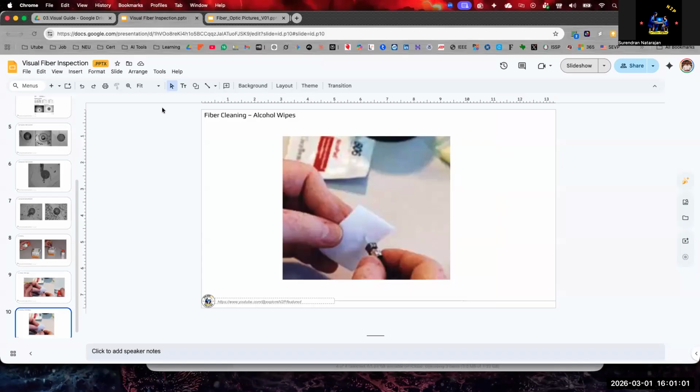The major part is safety in fiber optics. If you are going for a certification, safety is important. You saw that fiber is like a very thin hair. If it is broken, there are pieces, and you can't see those pieces on the floor. It is virtually impossible to see them. So it might be sticking in your hand. You wouldn't know, and by accident, if you swallow those things, that is a very worst case scenario. It may hit your eyes, nose, get inside your body. That is a very dangerous thing.